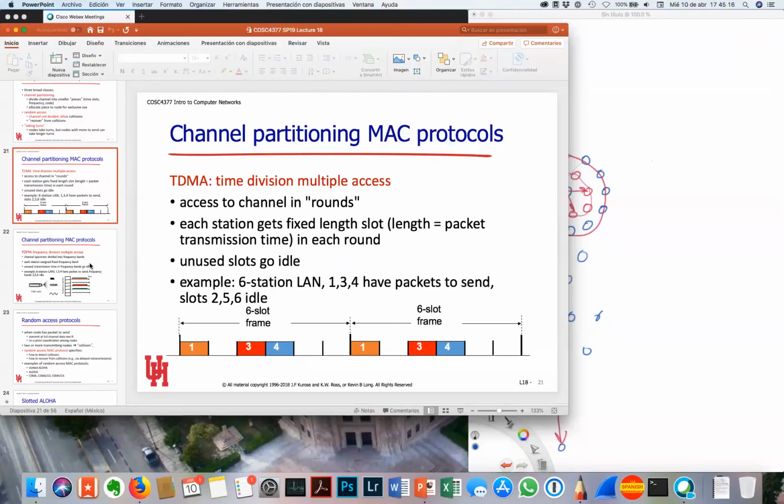You can transmit 8,000 of those packets, 8,000 of those chunks of 24 slots a second. Each person gets 8 bits in there. It's just a fairly small amount of data to send, but that's 64 KB per second. That's enough to digitize and transmit a phone call. So you can send 24 phone calls at a time with the device, because that's as many as we could figure out how to cram in there at a time. And so that's been around since, in practice, working for customers since the early 1970s. Hartford Insurance was the first one to get a T1 line in the world, outside of a lab.